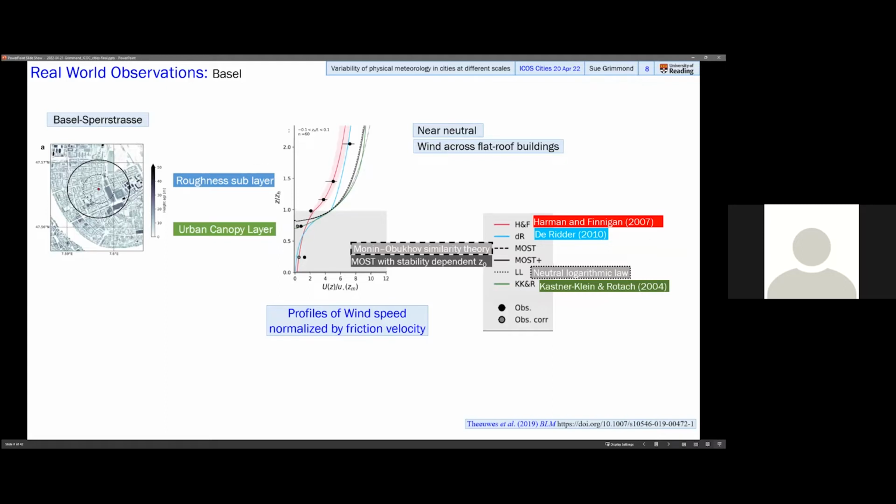So what the model is doing is typically the numerical weather prediction model, the climate model, links the surface model to the atmospheric model at the blending height, so at that boundary between the roughness sublayer and the inertial sublayer. In the inertial sublayer, as I said before, Monin-Obukhov similarity and the log law apply, but they don't apply within the surface layer model. Therefore, if we apply them, we expect the wind speed to go to 0 at the height where the roughness length and displacement height occur. So this means that it's roughly just below the mean building height shown here in the grey.